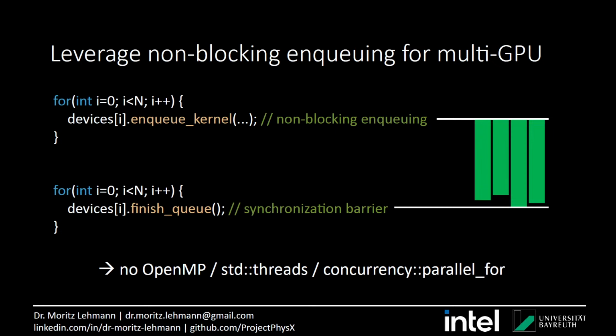Free slip boundaries means that the fluid can go over a boundary without sticking to it, so that the velocity directly on the boundary is not impacted at all. By default, Lattice Boltzmann has a no slip boundary, where the fluid velocity on the boundary is zero, or matching the boundary velocity. And there is an implementation where you do a specular reflection of the density distribution functions